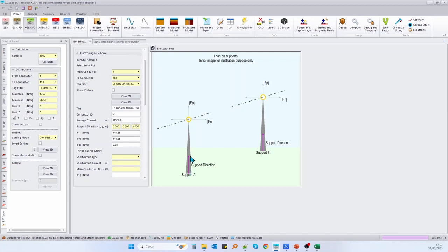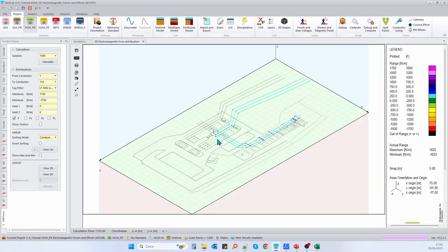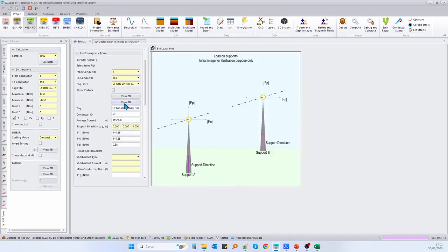It's not important that the direction is perfectly the one you have in your substation or in reality; it has to be almost parallel to that. So if, as in this case, everything is supported starting from the ground, the support direction will be this one, 0, 0, 1, which is the Z direction. And so we will have something which is stuck in the ground.